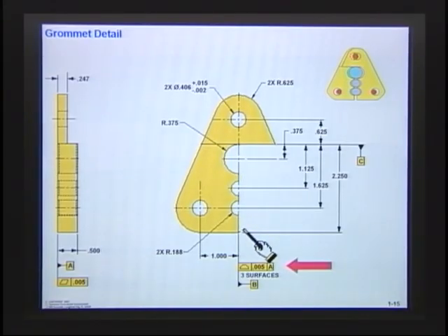If I put a perpendicularity, you know how perpendicularity works. This surface would be perpendicular, this surface is perpendicular, and this surface is perpendicular, but perpendicularity doesn't make anything in line. It just says this is perpendicular, so this may be perpendicular out, this may be perpendicular in, this may be perpendicular out.